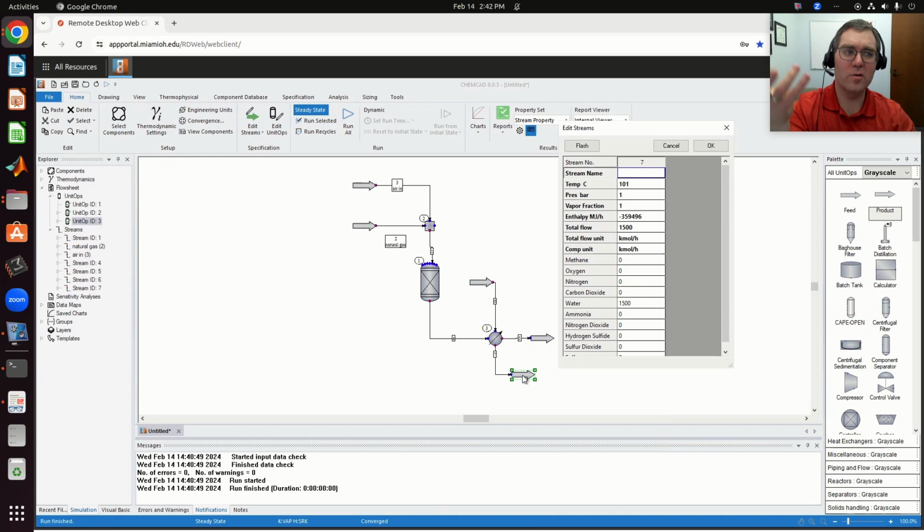But one thing you could do is, now that I have this heat being generated, I could recycle that back and use it to preheat my liquid stream going in. Preheat my liquid going into my stripper to try and drive off more of that ammonia and H2S. But this is just that flare. Okay, hope that helps. We'll play around with this more in class.